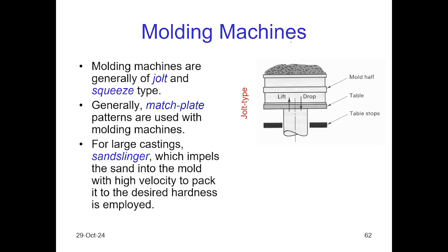Lift, drop. The jolting displacement creates impact forces, and those impact forces force the sand particles toward the pattern, and then achieve the squeezing stage.